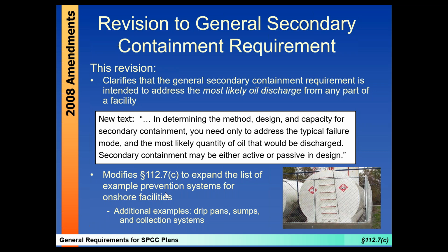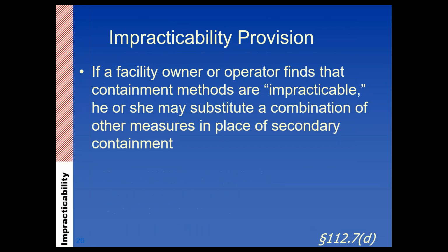And there's no freeboard requirement for rain events. So it's just kind of a general coverall. So there's a lot of flexibility, but there's a lot of room for taking risk. If you're a facility that's right on top of the water and you got piping there, you're probably going to want to take a very conservative approach to addressing containment, as opposed to a facility that may not pose that same risk, that may be quite a distance away from a water body. But again, it provides a lot of flexibility.